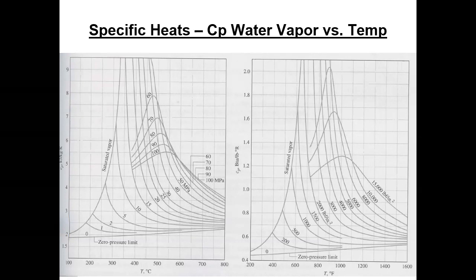So, as long as you're doing a delta T, you can go ahead and put degrees Fahrenheit or degrees C in it, whichever unit you're using. But if you're putting in one temperature, you better be very careful. Most of the time, if you're putting in one, using absolute temperature is the right way to go. Okay?